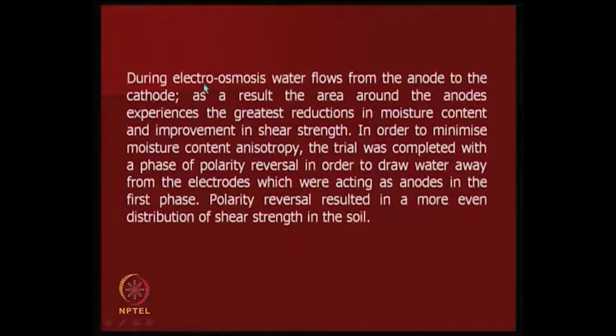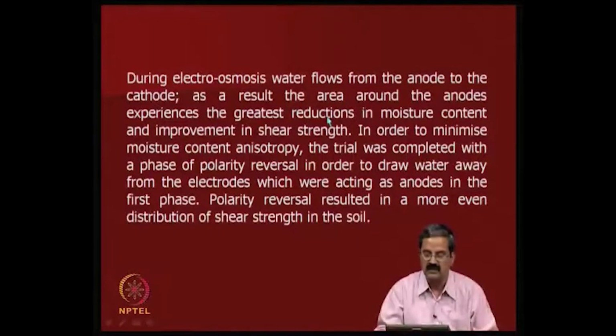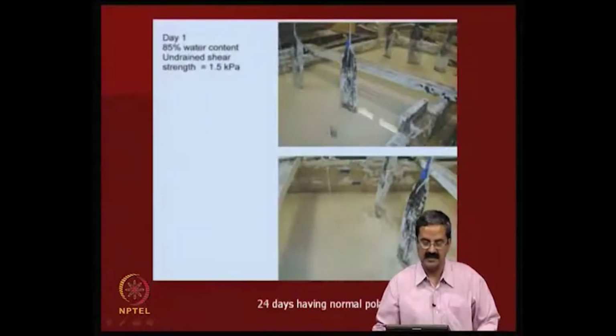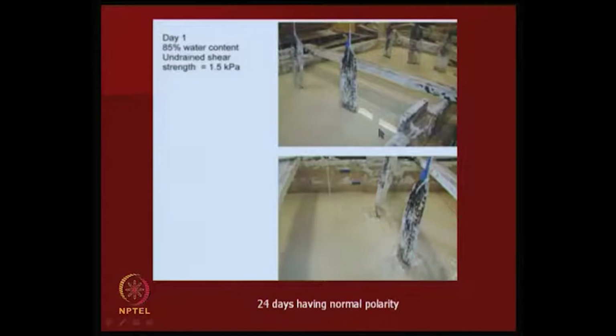So, they were able to observe, as we observed, the greatest water reductions in moisture content and the improvement in shear strength, and they are able to do some reversals also. You can see that with super soft soil, you take this slurry, and then put in prefabricated vertical drains, and undrained shear strength and all that is there.